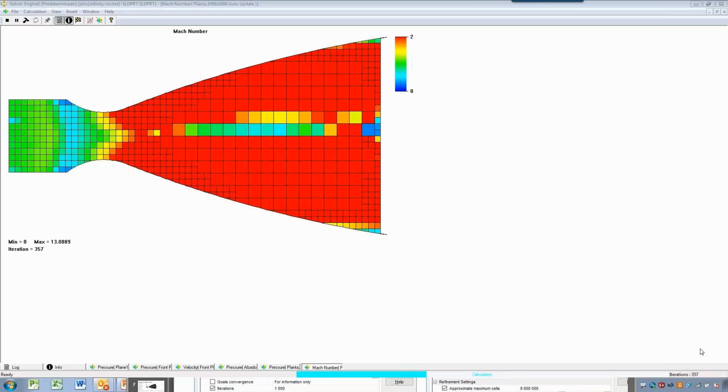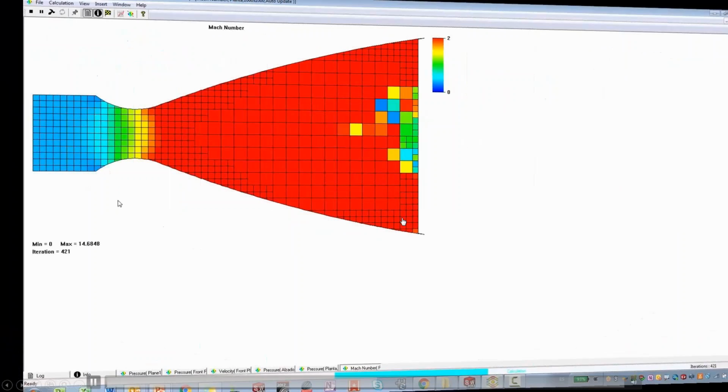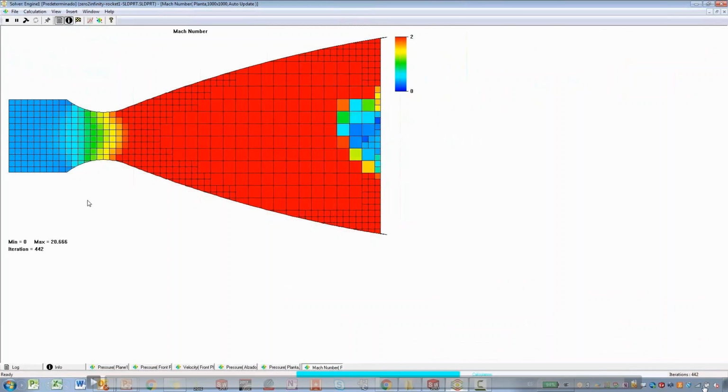But with the run here, with the internal flow, we can see clearly the adaptive mesh through the result, through the iterations, what SOLIDWORKS Flow Simulation is trying to do, and even we can have here more than 1000 iterations. So in my case here, because I'm expecting a supersonic situation in the flow, I'm having more than maybe 1000 iterations.